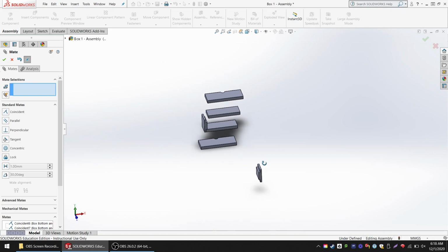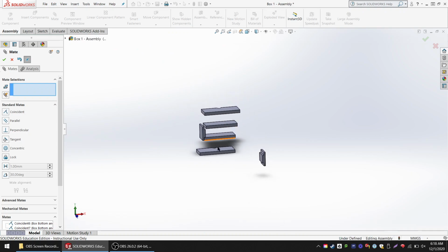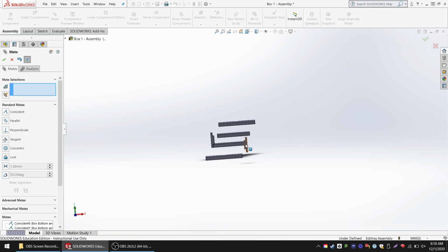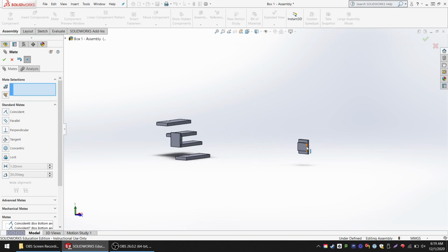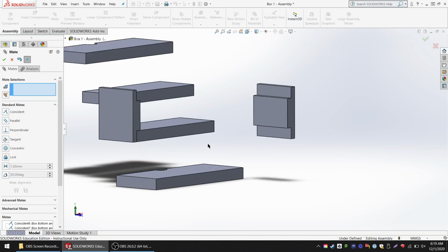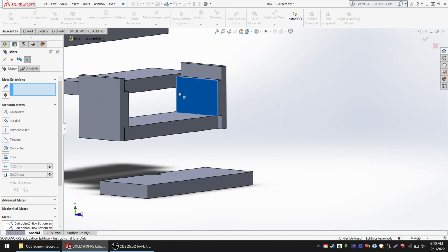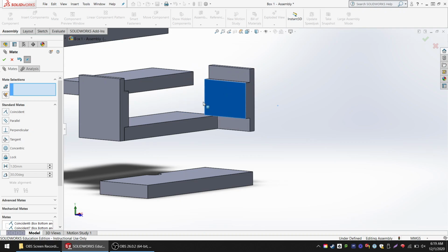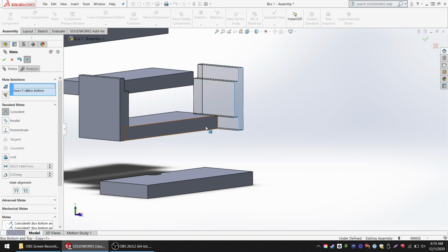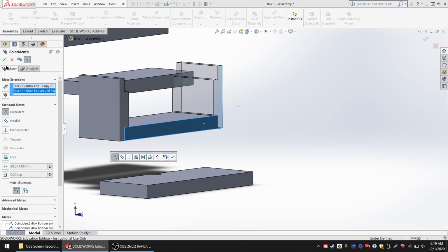This is when the assembly can be a little bit confusing. Did you see how that moved way out far? When you're moving these pieces around by hand, it's really hard to tell where they're actually at, because this looks like I'm moving it up and down, but I'm actually moving it left and right, because we have that locked in. The tricky part is just deciding which mates to do. So the only one I need left here is this side, and those will also be coincident.